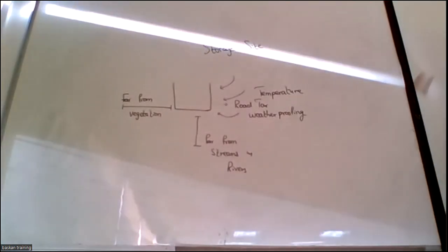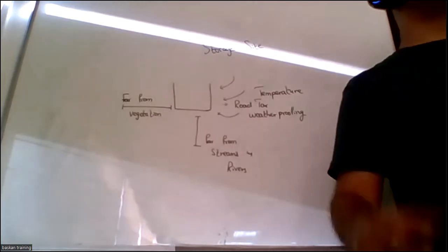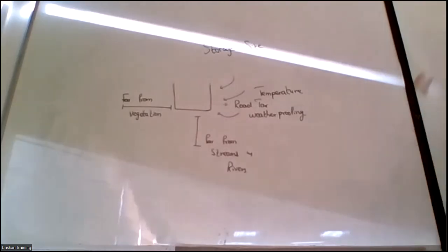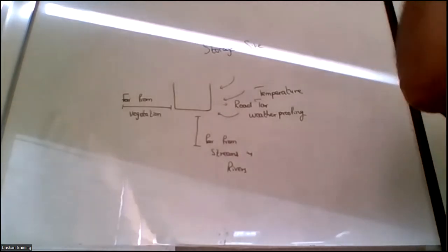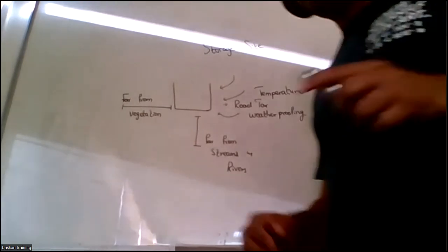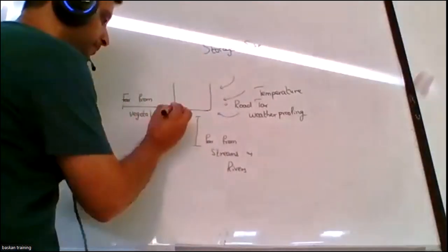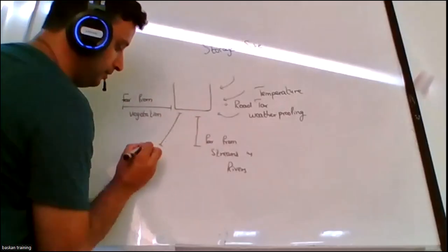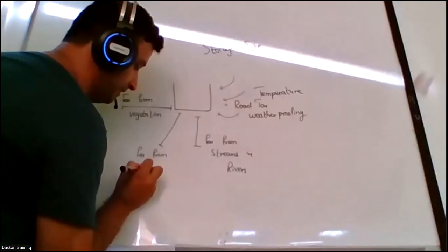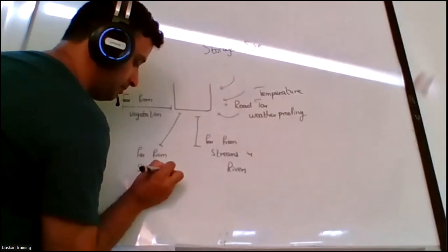In hot weather, water gets heated up and the surrounding air becomes moisturized. We've discussed moisture, we don't want that to accumulate, right? Moisture accelerates the oxidation process. We don't want that. Any type of steam lines, like hot pipelines, should not be traveling near the silo. That may heat it up.